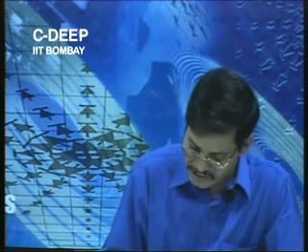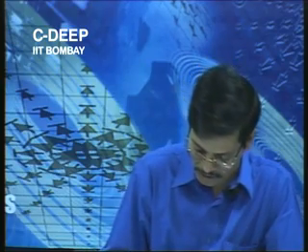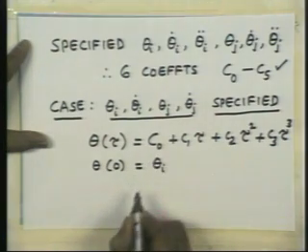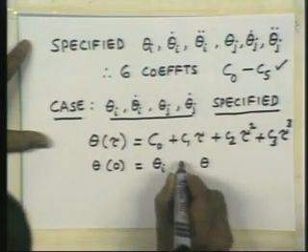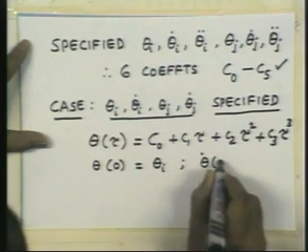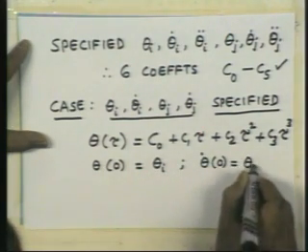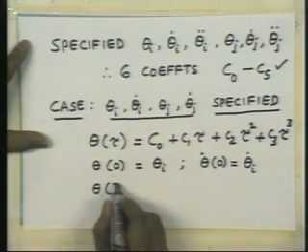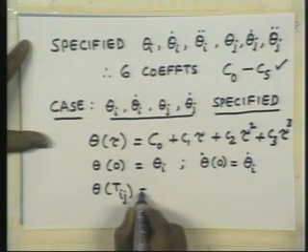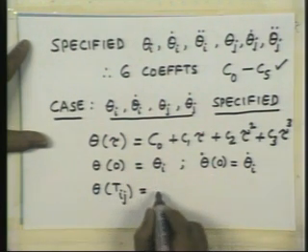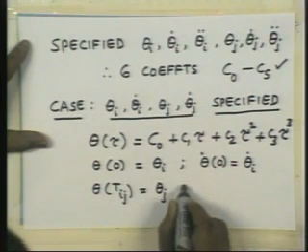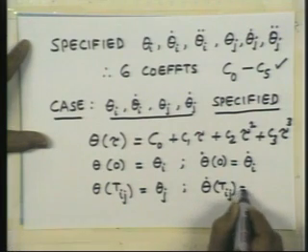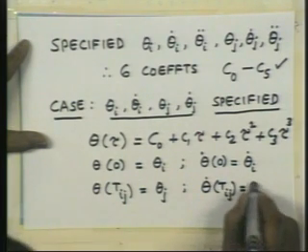So, the constraints that I have on theta and theta dot can be written as theta of 0, that is the ith position, theta I; theta dot of 0 is theta I dot; theta corresponding to the time duration between the points, Tij, is theta j; and theta dot corresponding to the end of the motion is theta dot j.